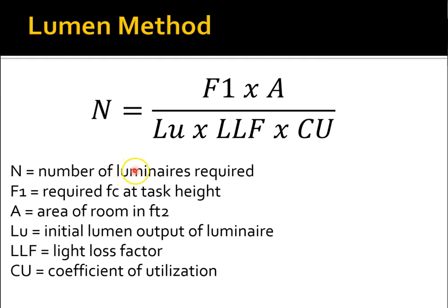The other somewhat common way to use this is if I'm looking for the illuminance, the brightness, right here. You can use the equation for that as well. If you know the number of luminaires and all these other factors, you're like, okay, we have 15 luminaires, and here are the dimensions, etc. How bright is this desk going to be? You can use it for that as well. But we're going to use it to determine the number of luminaires.